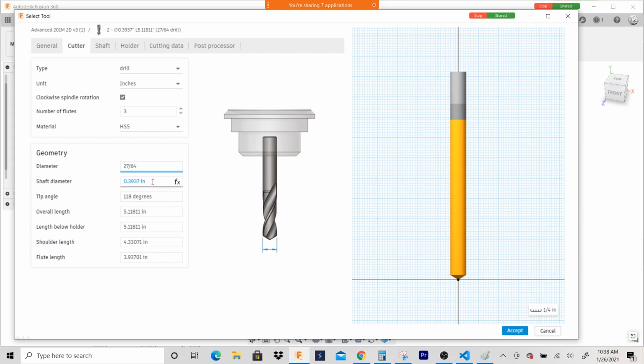I mean, you'd be 1/1000ths bigger. But usually if it's just a through hole, 1/1000ths isn't going to make a difference unless the print specs require something more.